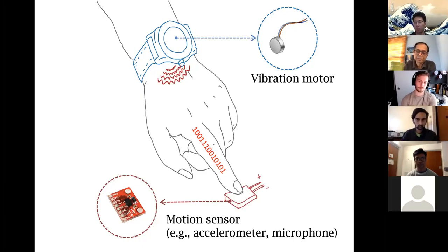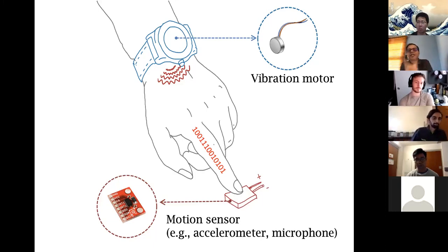Questions? I just had a question about the Nyquist sampling rate. Technically, don't we only have half of the frequency? Exactly. So it's only like 2 or 3 bins. What you do is you say, I have a 200 hertz sampling rate at the accelerometer, so I really have 100 hertz. Okay, I get the example though. Exactly. So you divide 100 hertz into 20 hertz bins, that's 5 bins.